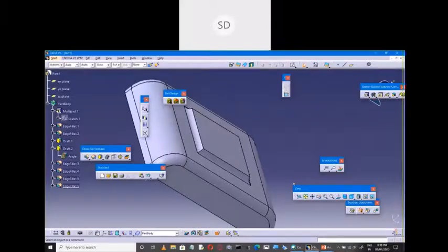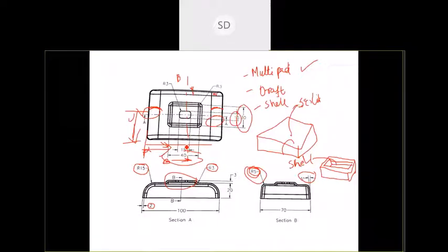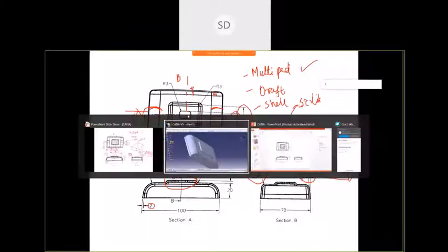Now, if we need a hole here, look out. Now the hole dimension here is 10 and 15. It is a rectangular hole. Let us go for a pocket. You can carry out the pocket after the shell command, because if you created the pocket earlier, it is going to remain at its thickness at that particular position.